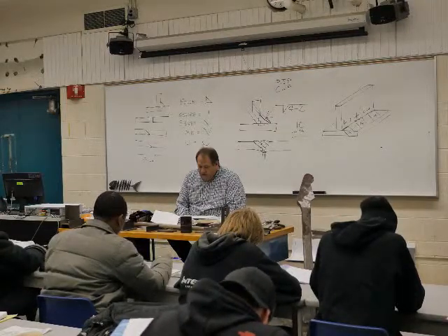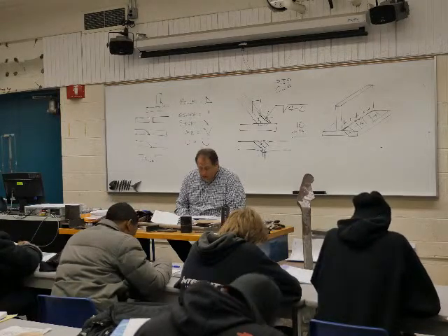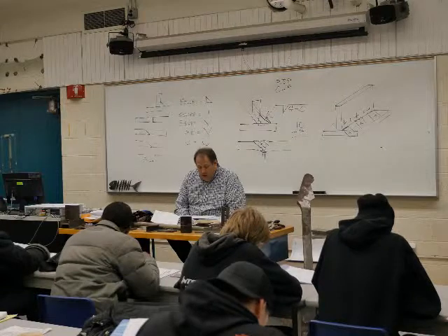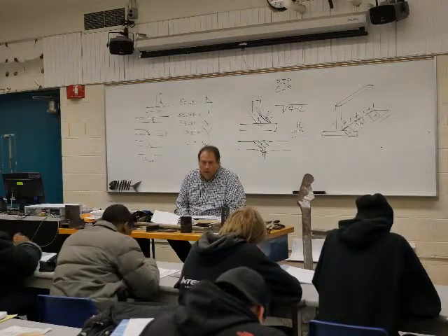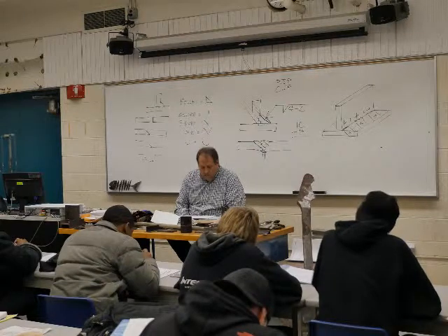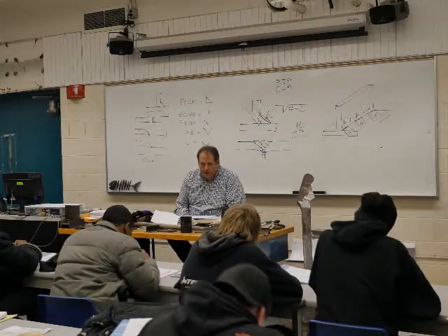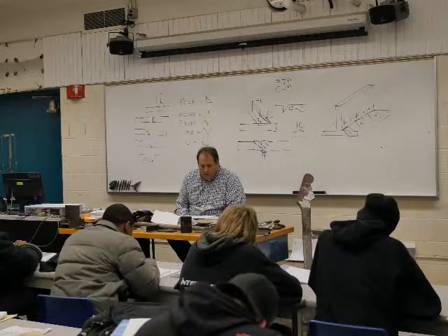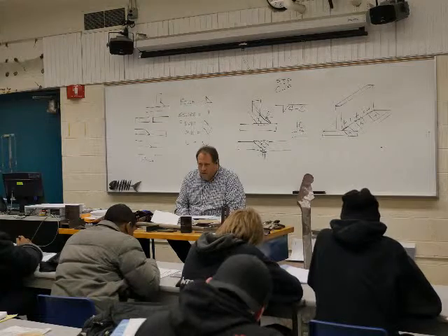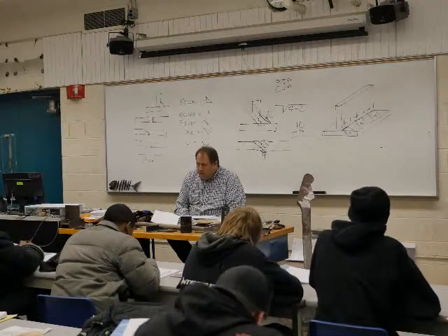Okay, let's look at that top section where it says cable drum. How many weld symbols do you see there? There's 2 on that top section, all the way around, with fillets. Yeah, 1/4 inch fillets.